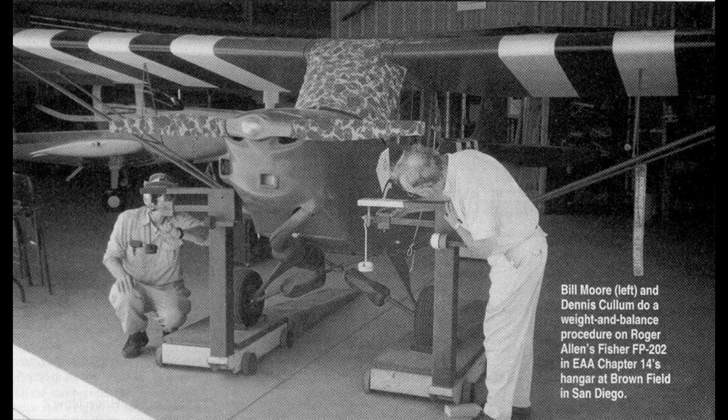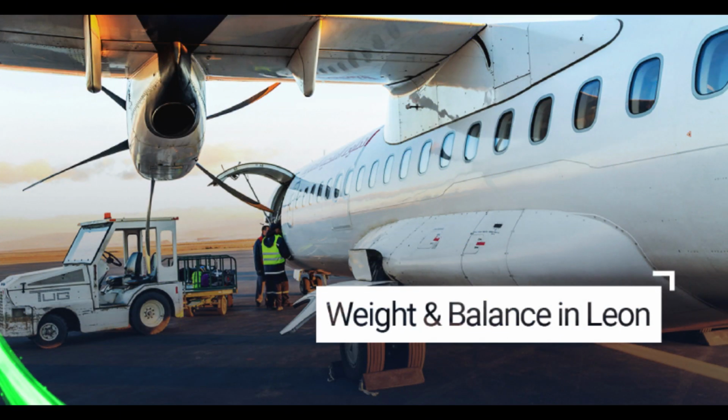Record the new empty weight center of gravity, EWCG, data in the current approved aircraft flight manual or issued operating limitations. When an aircraft has undergone extensive repair or major alteration, it should be reweighed, and a new weight and balance record started. The A&P FAA certificated mechanic or repairman responsible for the work must provide the pilot with current and accurate aircraft weight information and location of the EWCG.